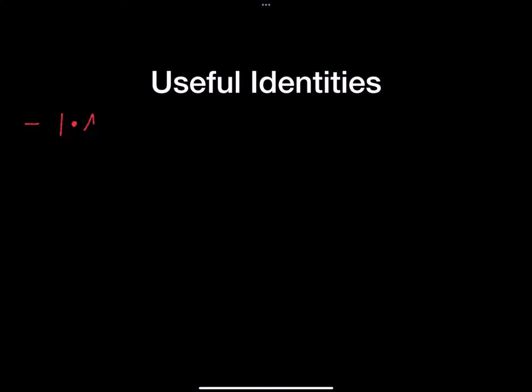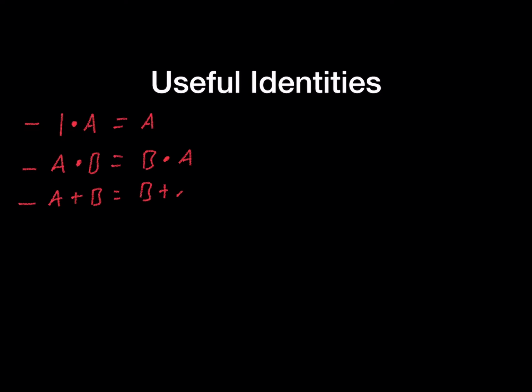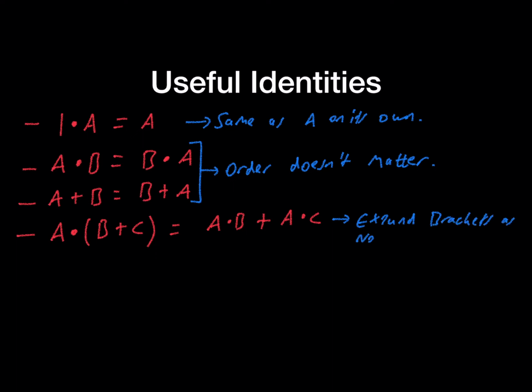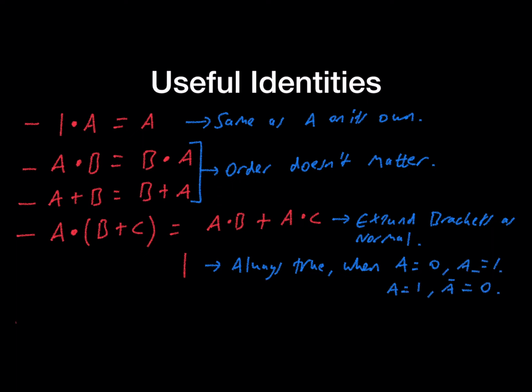These are some common and useful identities to use in Boolean algebra. The main point of this type of algebra is to simplify and get as few gates as possible, or realize a sum of products expression using only a certain type of gate. We start by stating some obvious points. 1.a says that the output is only true dependent on a, as the other input is always 1.